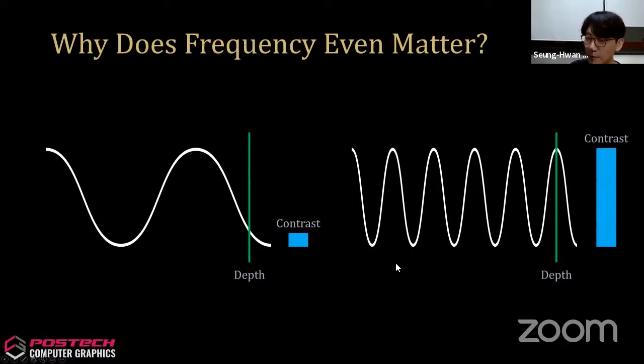However, in previous time of flight imaging systems, it was too difficult to utilize this high frequency modulation because of the inevitable noise in the photon to electron conversion that I just described. In our work, because we moved this correlation computation from the analog domain to the optical domain, we are now much more comfortable with handling the noise. So we can increase this modulation frequency quite a lot to achieve high depth sensitivity.